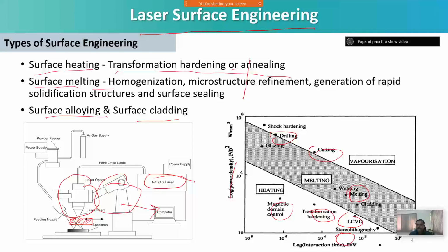Then you can vaporize and get any kind of cutting action. When you want to do some kind of welding, possibly you can work a little away from the focal point, as your intention is not to vaporize the material, but just to melt the material to realize some kind of fusion. And if you want to do some kind of surface treatment, then obviously your defocusing position will be a little more, and you like to get the possible reaction by appropriately reducing the energy density according to the process requirement.